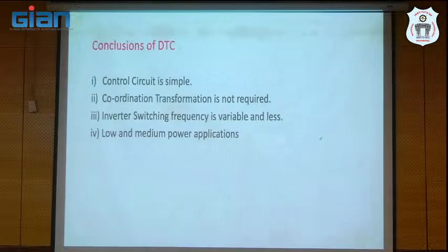Advantage is the control circuit is simple, transformations are not required. Next, the inverter switching frequency is variable, but that is no problem for drives application. We do not need to bother about the switching frequency. This is also fine. In general, for low and medium power application, they will adopt it. But what are the limitations here?